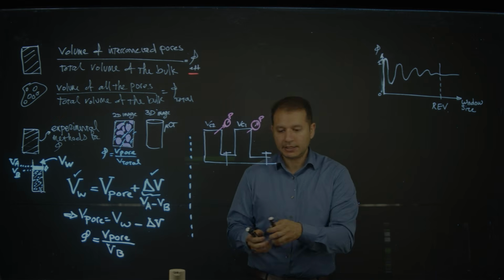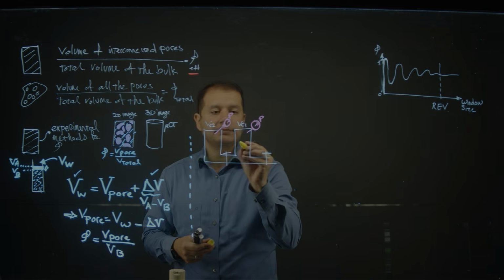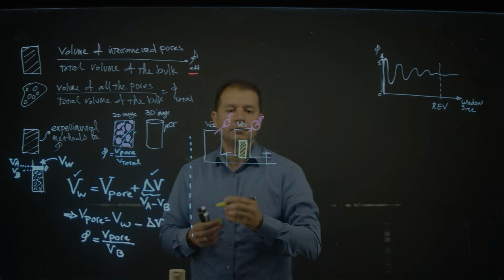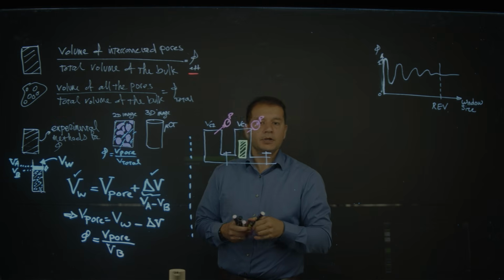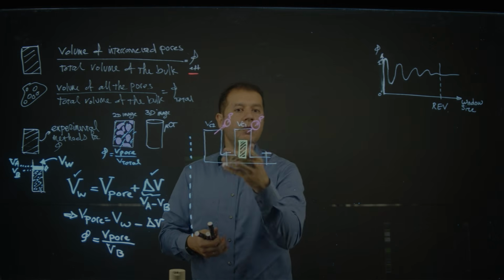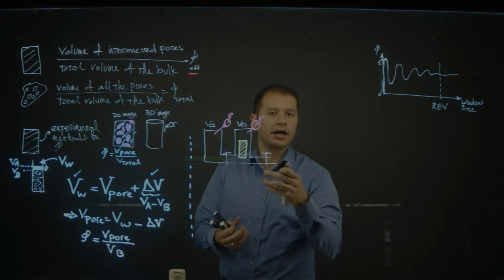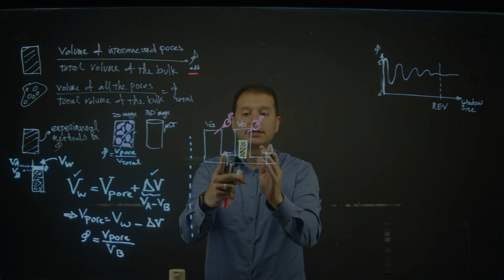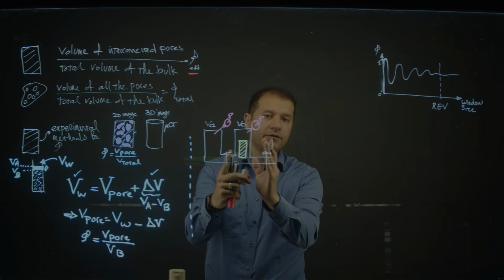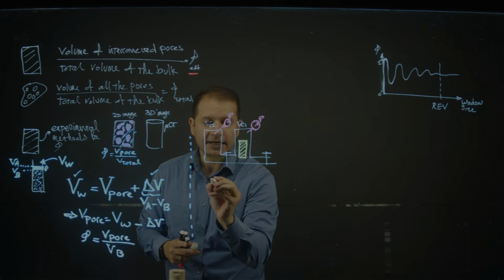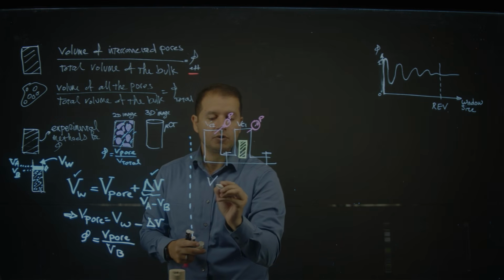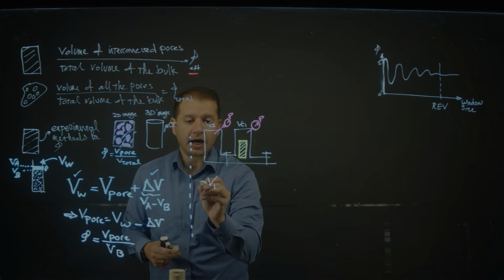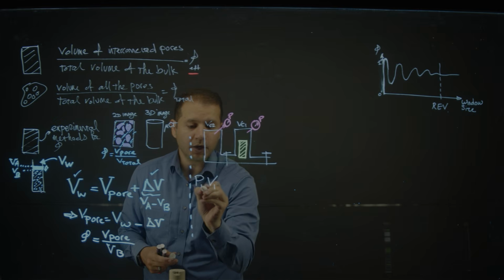At the very beginning, I am going to place my rock sample in chamber 1. This is my rock. So when I flow in my helium, my air at low pressure, I know that my gas is first contained in the first chamber part. So I take the volume of stage 1 of my gas, V1, times the pressure P1.